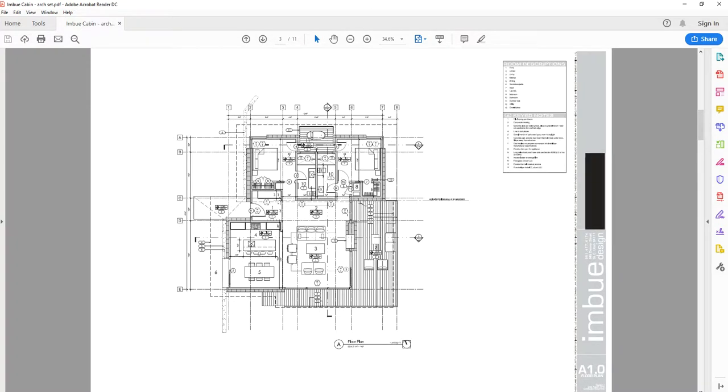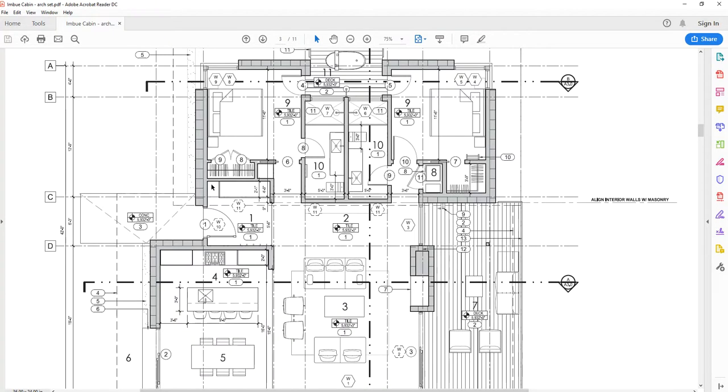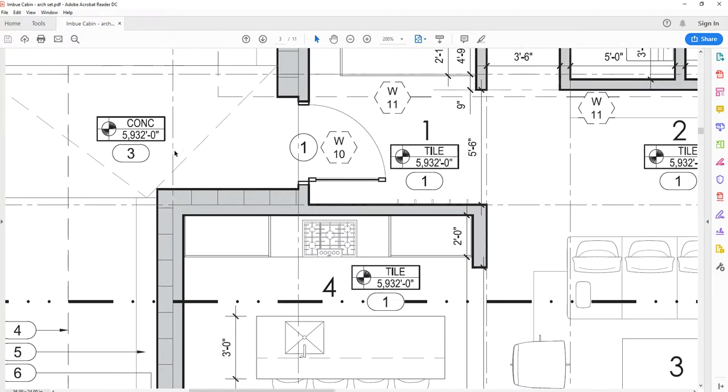So I'm going to go back to the floor plan, and I'm going to think about how to draw this now, right? You've all done an exercise and worked on this. But now I have these grids that can help me draw, right? And I'm going to look at how these grids sort of interact with my walls, and I'm going to draw them the best I can. So as I look at this wall assembly, I notice that the grids are not lined up with the outside of the wall. They're lined up with that wood stud, right? Which is the core boundary. That's what it's called here, okay?